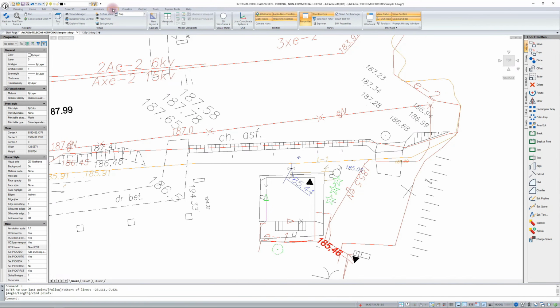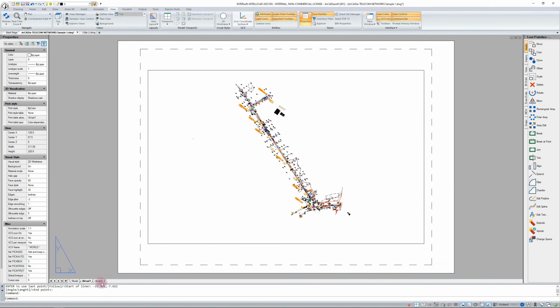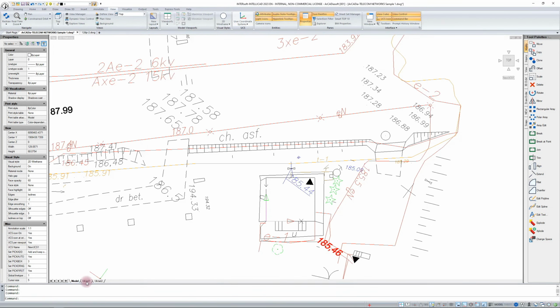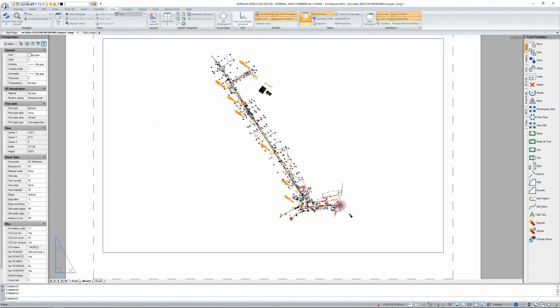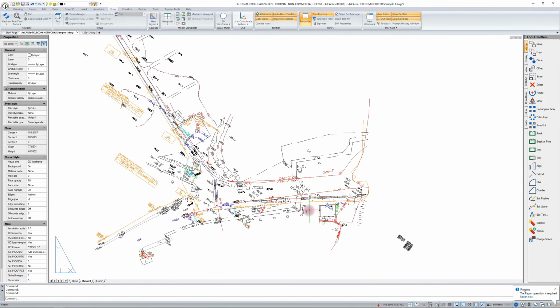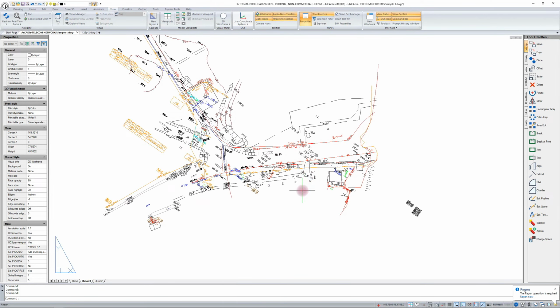This also allows me to enter local coordinate systems on our sheet. For example, one sheet is the world global coordinate system, another is the local one. In another one, I will define, for example, here the local layout. I can switch between them, and the printouts will be just these set views.